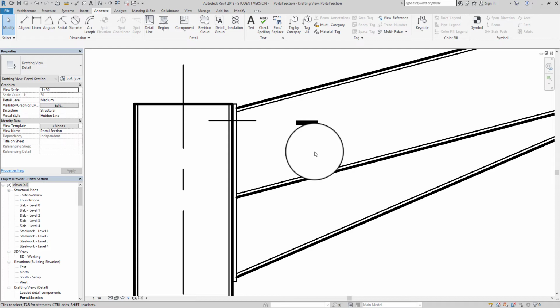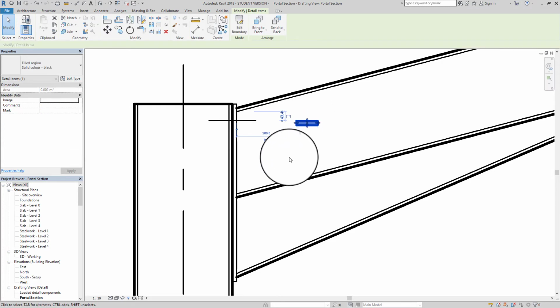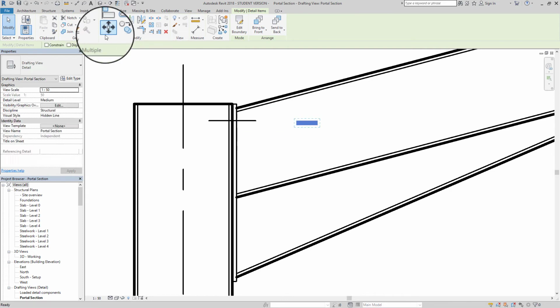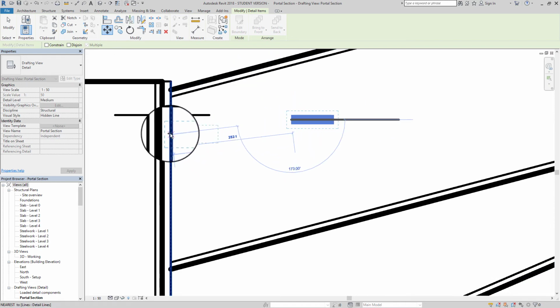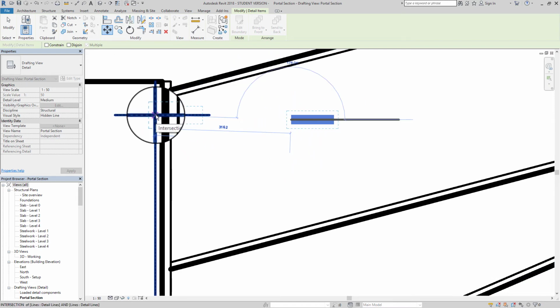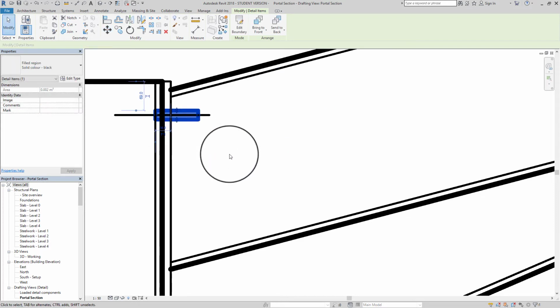It's the wrong length at the moment, but as I've said previously, once you've drawn it, you can then edit it accordingly. So we're going to pick that one up, we're going to move it. So we're going to move, and we want from the midpoint, so again, the little red triangle, and we want to move it to the intersection of your centre line and the column flange.